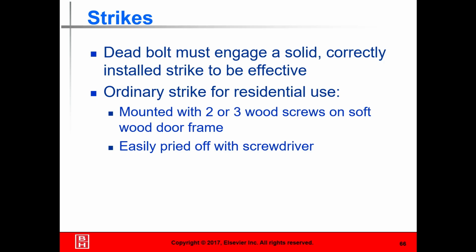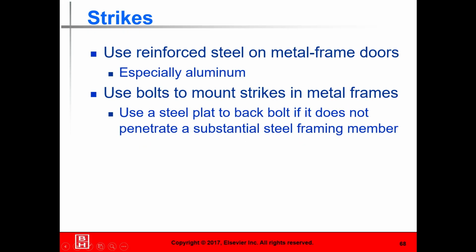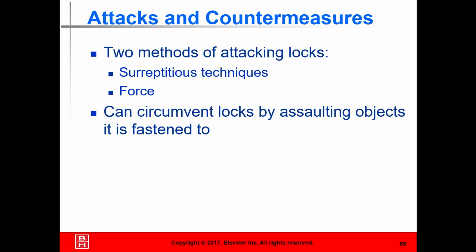High security and wider strikes incorporate a lip that wraps around the door, usually with 3-inch screws, and the screws should be in line. They are used to reinforce steel and metal framed doors, especially aluminum. Use bolts to mount the strike in metal frames. These are some of the different things.